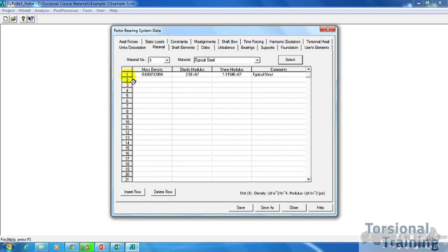So what it does is it populates this first row, and the mass density that it calculates is 7.32 e to the -3, I believe. And it leaves the density. Again, don't forget we're dealing with consistent English units, so we have density in terms of pound force second square over inch raised to 4 instead of the classic pound mass over inch cube. And the shear modulus 1.154 e to the 7 psi, pound force over inch squared, and the elastic modulus.